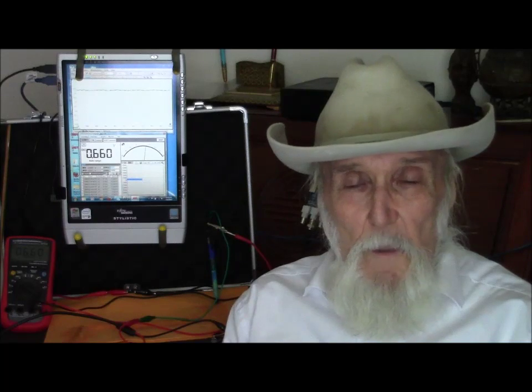The idea is that we measure the voltage between the ground and the pipeline so that we can estimate if the equilibrium between the pipeline metal and the ground is such that current, electrical current, is flowing onto the pipeline and not off the pipeline.